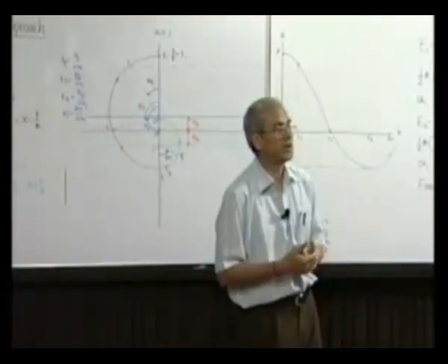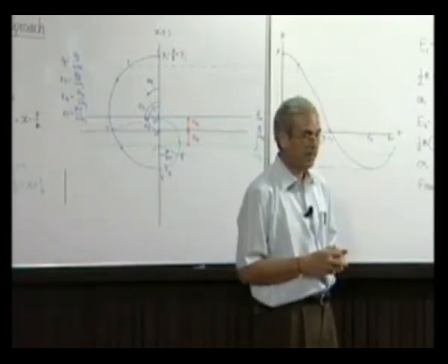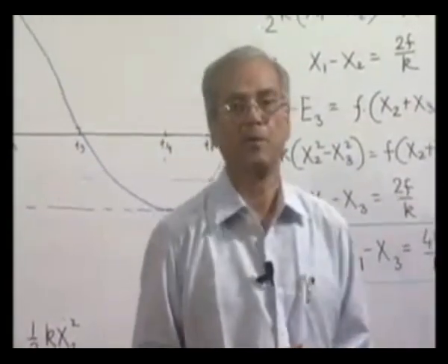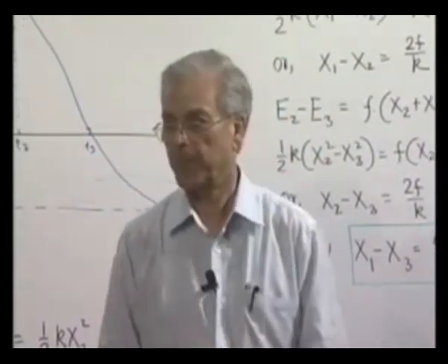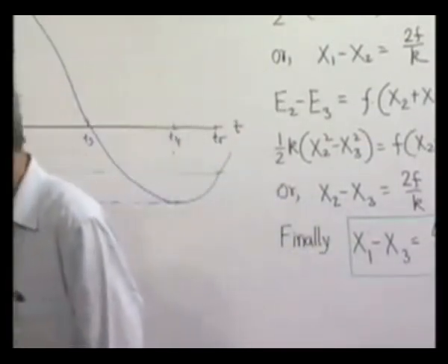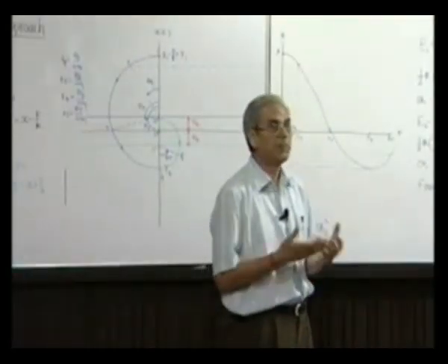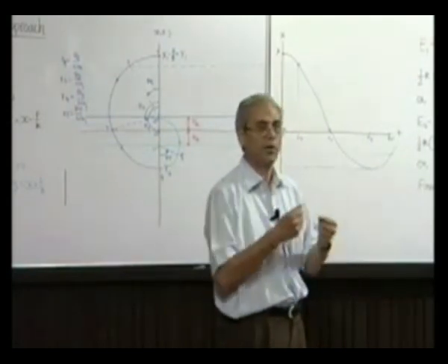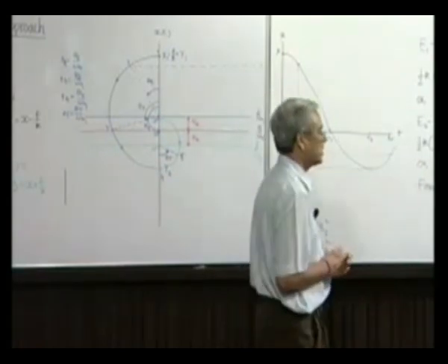If the damping coefficient of the system is above that, then the response is aperiodic, but if it is less than the critical value, then the system is periodic, though with decreasing amplitude with time. In the next lecture, we will start the determination of the response of a system to outside oscillating disturbance or force. That means we will start our discussion on forced vibration.